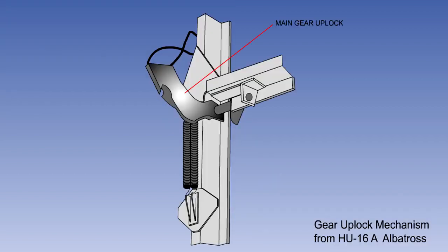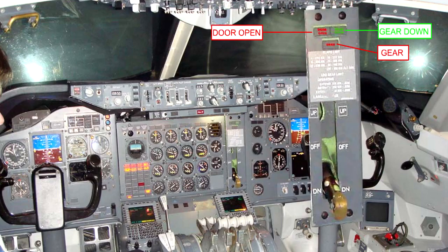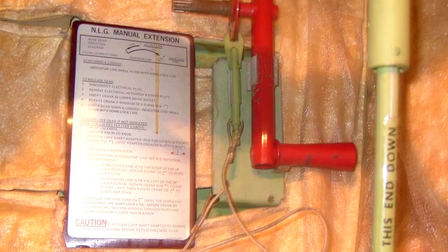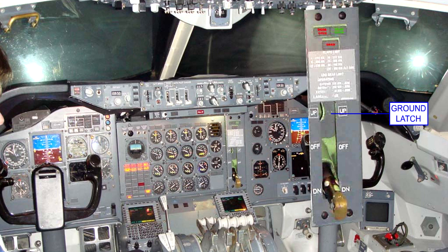used. A retractable landing gear is provided with mechanical locks to ensure that each leg is locked securely in the up or down position. It will have a means to indicate to the crew the position of each leg and a means by which the landing gear can be lowered in the event of the failure of the normal power system. In addition, a system is provided to prevent retraction with the aircraft on the ground, and warning devices are fitted to help guard against landing when the gear is retracted.